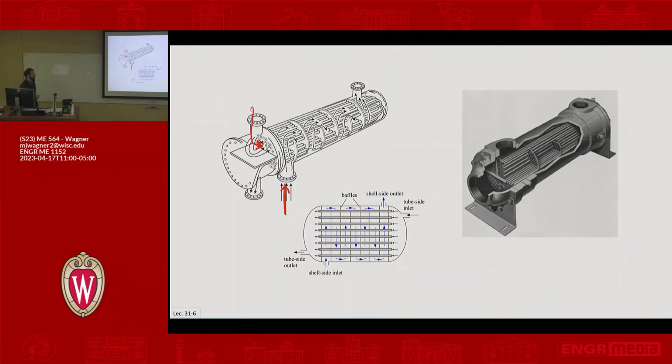So some in the classroom might be familiar with molten salt to steam heat exchangers. This is used for concentrating solar technology. It looks exactly like this. So you have steam coming in on this side. Steam is contained within these tubes. And then you have a really hot molten salt, and you're trying to boil the steam. So the salt comes in, and in order to get good heat transfer, you want a relatively high velocity. So they achieve that by putting these baffles in and forcing the fluid to go back and forth.